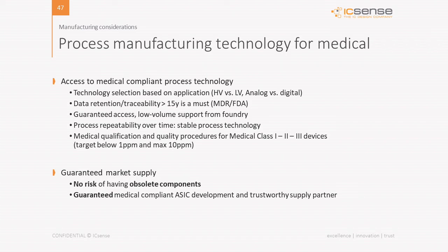MDR and FDA request more than 15 years of data retention. Check with your foundry if that's the case. Not all guarantee as such. Also, guaranteed access and low volume support from the foundry is essential. Also, process repeatability over time. You want to have a stable process where, within a number of years, the same behavior is expected.